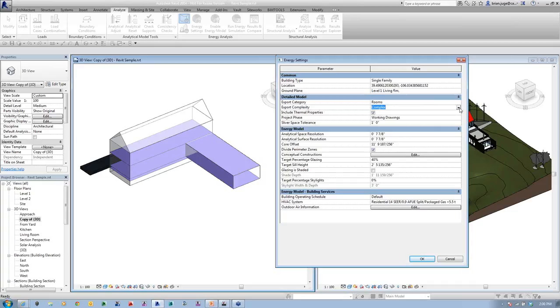Brian, if I might, rooms and spaces are kind of important, at least for the design industry, because architects are going to tend to work in rooms, MEP people are going to tend to work in spaces, and it's going to define how the Revit model is set up a little bit differently, and perhaps some of the results you'll get. So you do want to take that in stride, rooms, spaces, things like that, as you're working with this. Yes, that's definitely important.